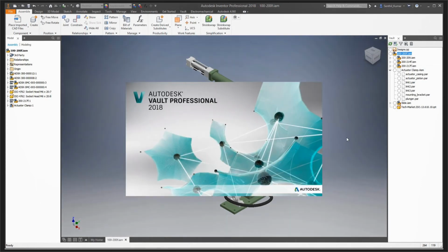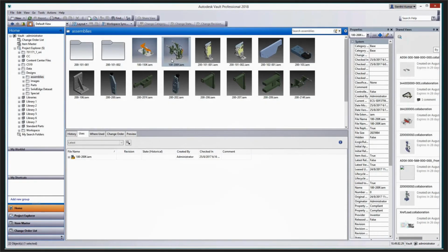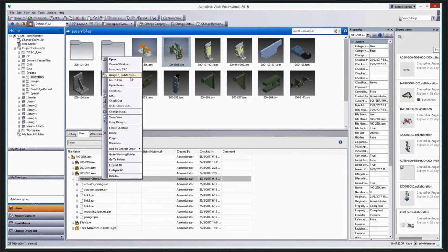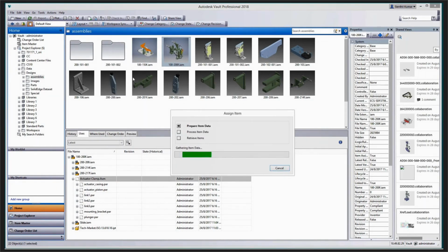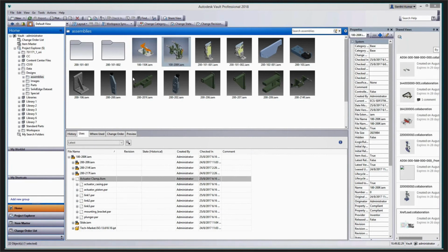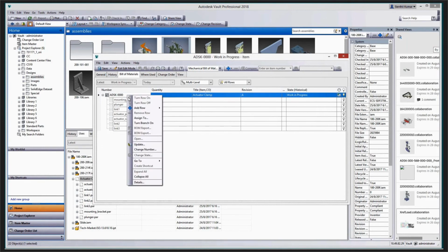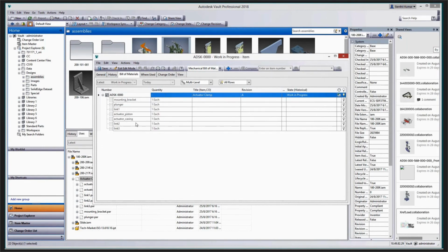If you go to that Vault folder, it's going to open an instance of Vault Professional there, and it's going to be able to see that, hey, your Solid Edge data is referenced by AnyCAD, and you've got full where used and used in capability as well. In addition to that, you can even execute assign item capability on these Solid Edge assemblies, even if you do not have a Solid Edge specific add-in for your Vault implemented.